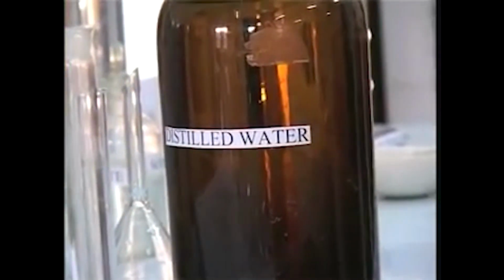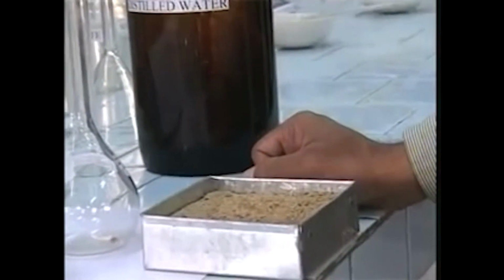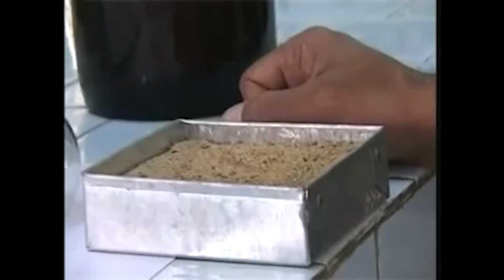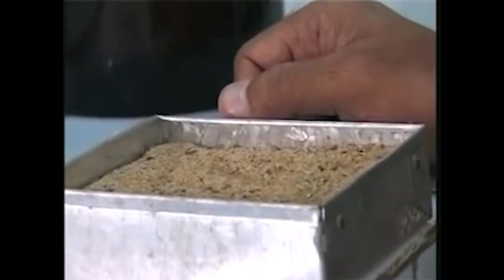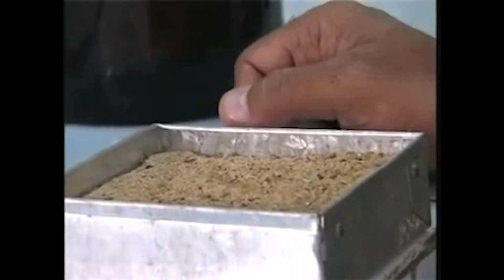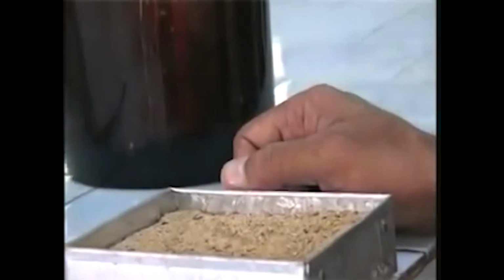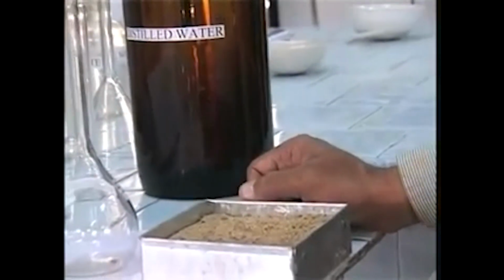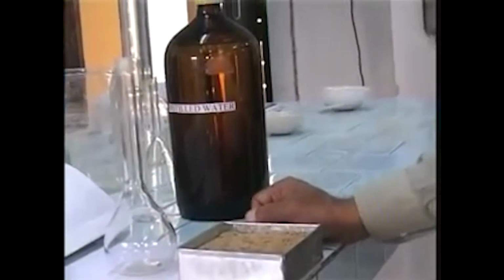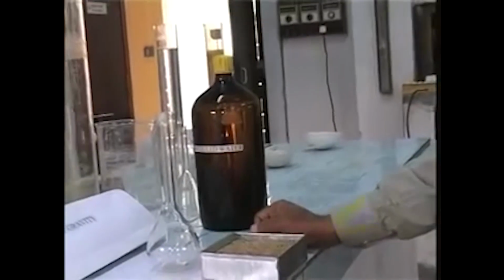We are going to take a representative amount of soil in the flask, and then we are going to top it off with distilled water up to the mark that we saw there on the stem of the flask, and we are going to keep it under suction to de-air the water so that there is no bubble of air included in between individual grains of the soil, because that is going to introduce some error in the reading.